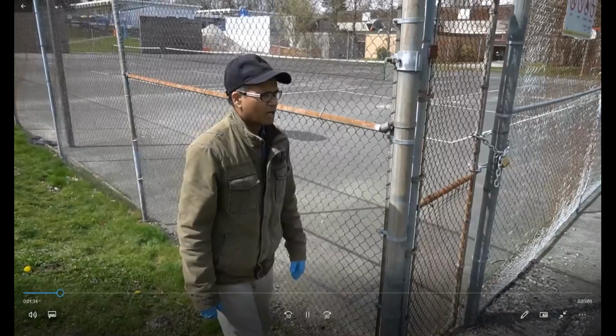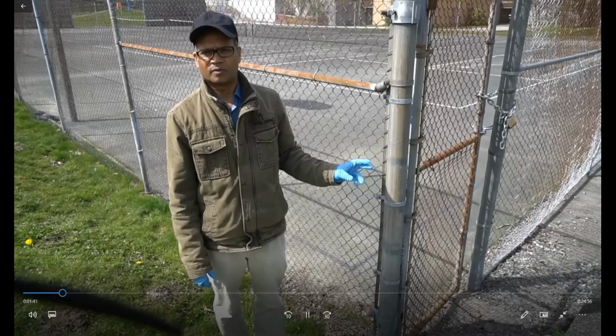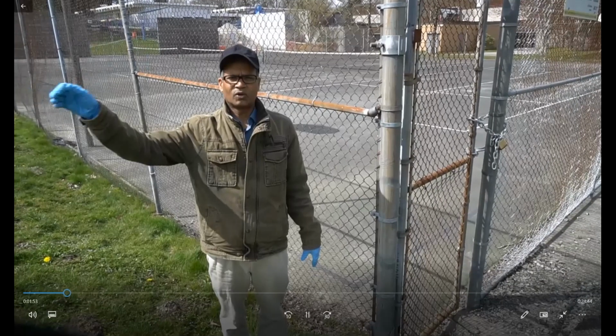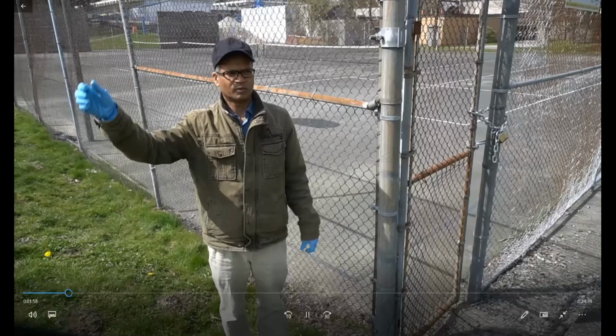What is the grounding point? Usually it is the grounding point of the transformer. From there we go any suitable distance, which should be 5 to 6 times the perimeter of the substation. At that distance we put our probe there.